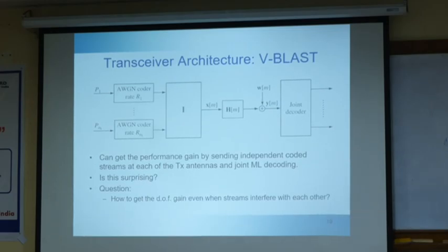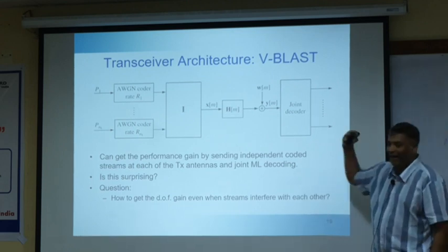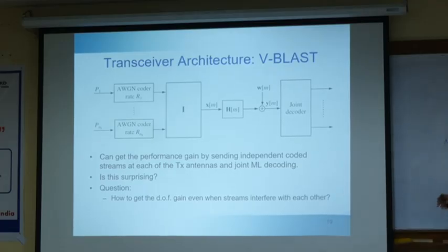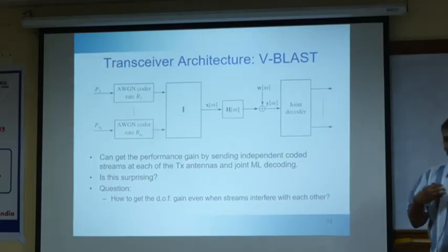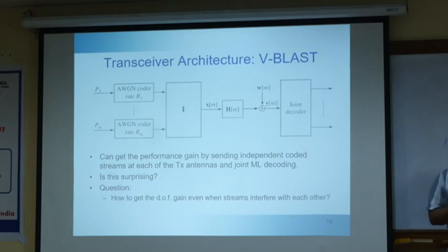So then we look at this slide at the end of the class. The channel capacity shows how much capacity gain we will get from the MIMO system. But how to realize that capacity is what we are going to see today. It's saying for 4 transmit antennas and 4 receive antennas, we can get 20 bits per second per hertz at 20 dB SNR. So how do we get that 20 bits per second? That's the thing we are going to see today, which is the architecture that achieves that capacity for the fast fading channel.